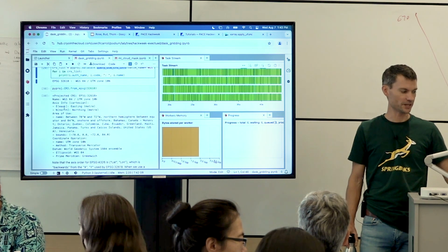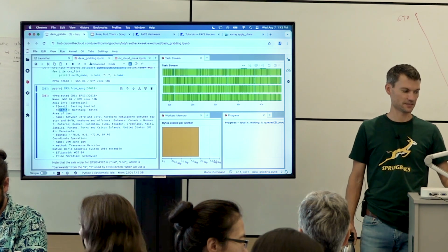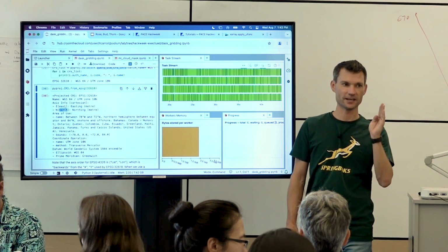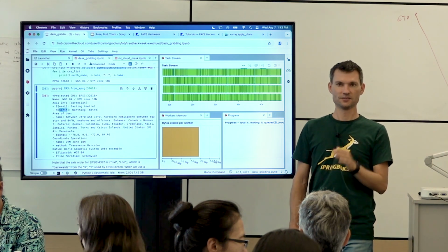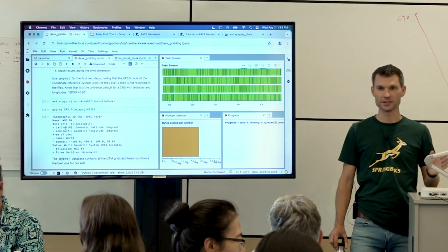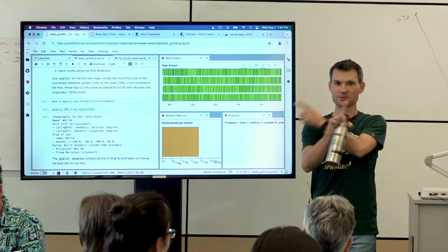It's important to note when you're playing with these things that the order of axes is defined in these sorts of data things. So this is easting and northing. That's the order you get. X is easting and Y is northing. For the other one, you get latitude, then longitude. You get north-south, then east-west. Don't swap those. It's easy to do.